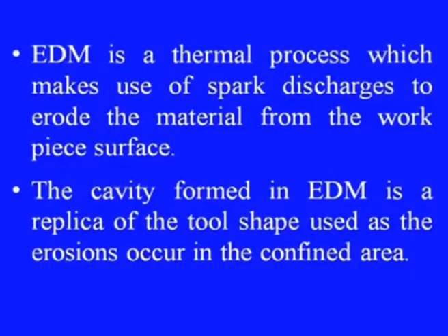Basically, EDM is a thermal process, as I have already indicated, which makes use of spark discharges to erode material from the workpiece. The cavity formed in EDM is a replica of the tool shape used, as the erosions occur in a confined area. We will see in detail the mechanism involved in this process a little later. Since spark discharges occur in EDM, it is also called spark machining or discharge machining.